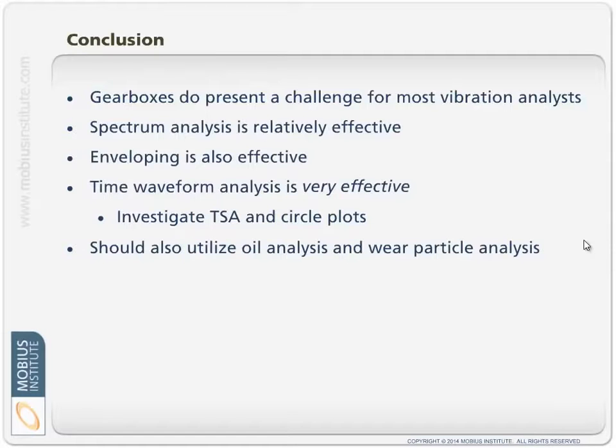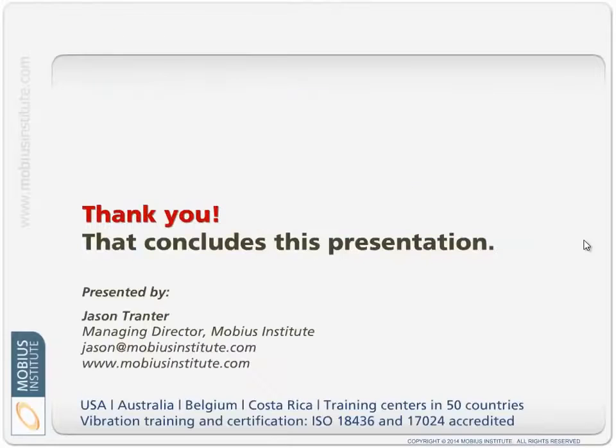Think about the criticality of the gearbox and how important it is that you get all this right. Think about the failure modes and the PF interval to make sure you're taking your measurements frequently enough. And also think very carefully about oil analysis to make sure it's being lubricated correctly without contamination, and wear particle analysis, so that you can detect those particulate contaminants but also detect any wear that's going on.